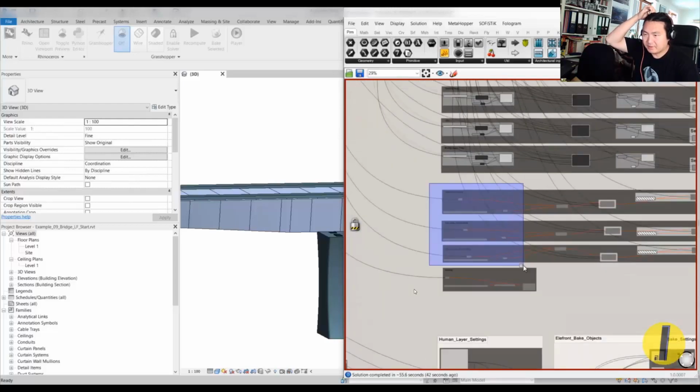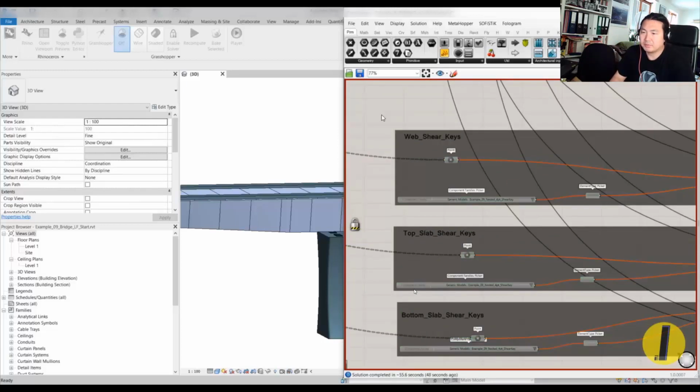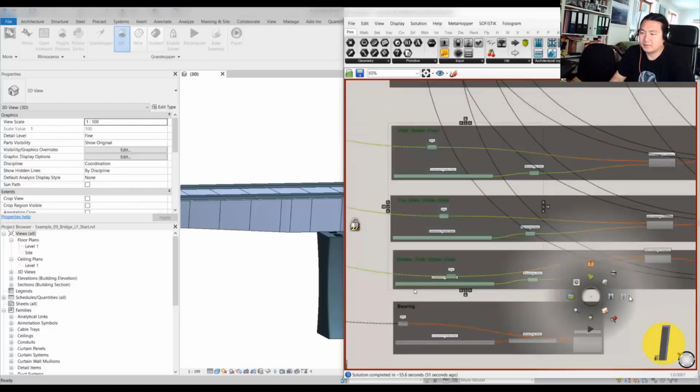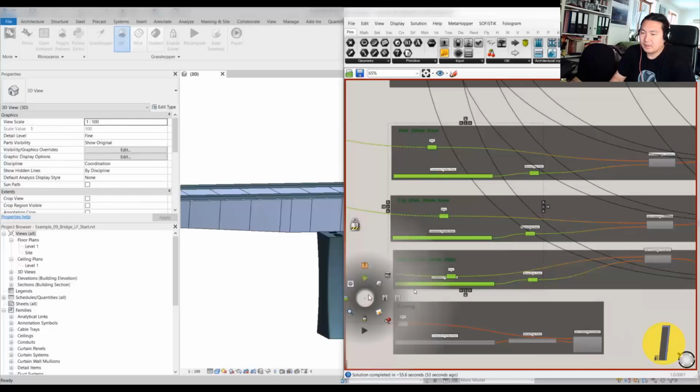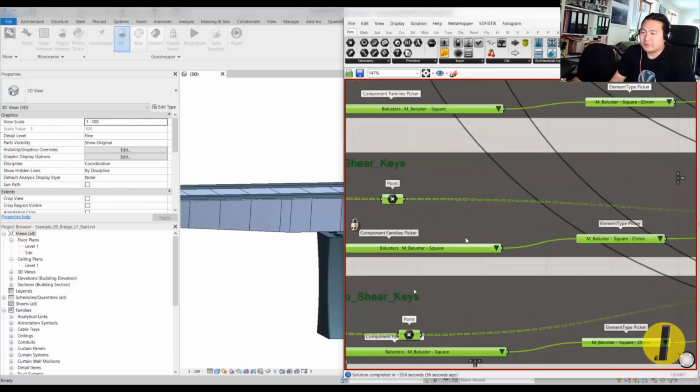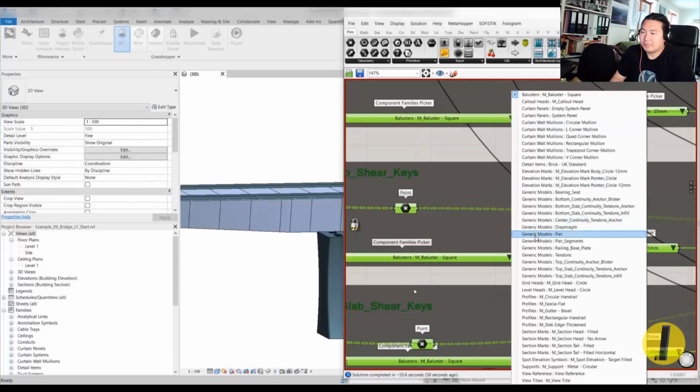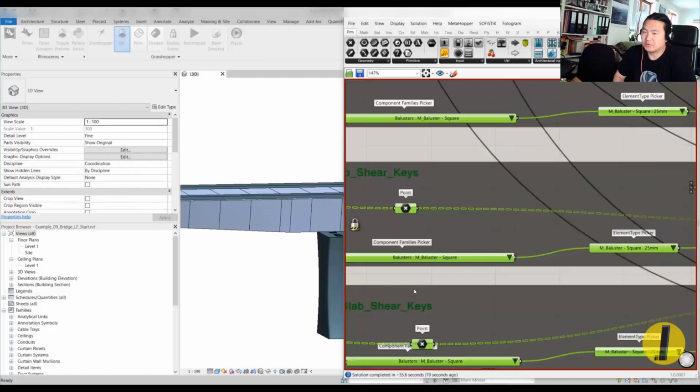But if you graft the data structure in Grasshopper, then every single segment will be applied as one section. Right, so it's just for the demonstration. You can see the shear key of the connection part. Of course, you can make a very detailed model, but I just decided to use an adaptive component and populate the location of the shear key so that you can annotate or tag in Revit.